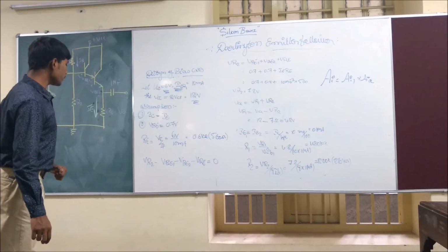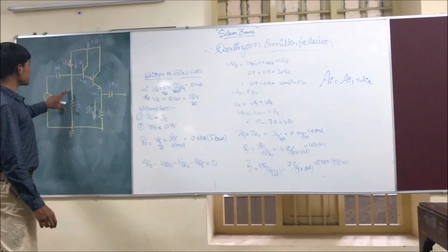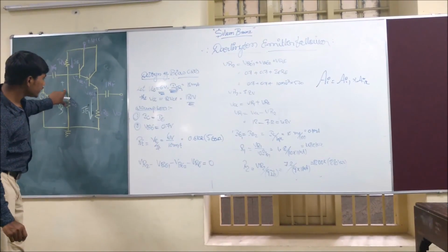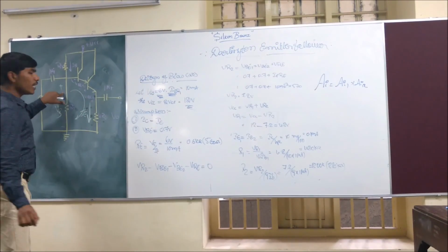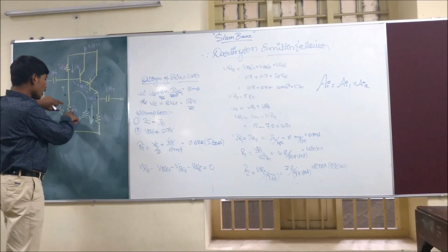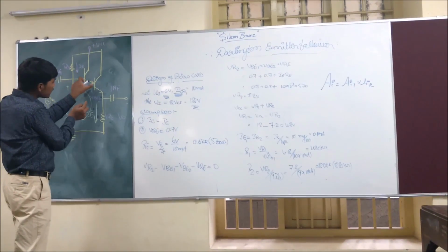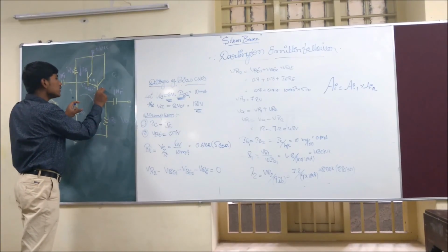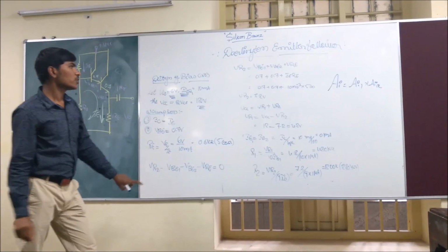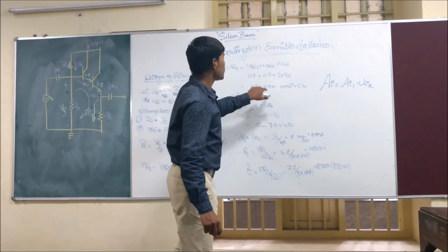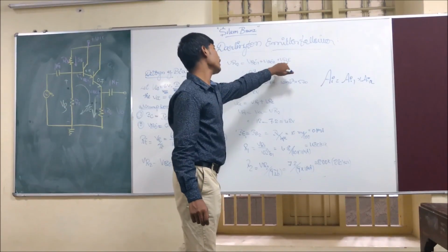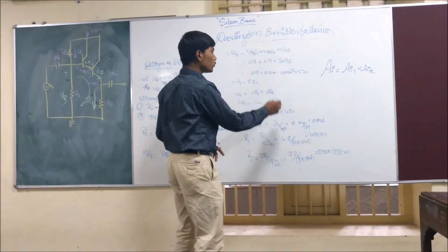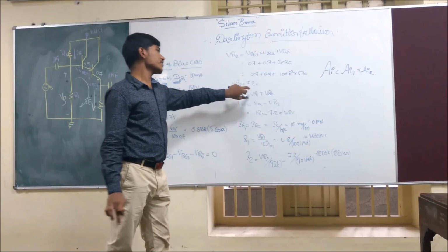The next step is the voltage across this, my biasing voltage. Let's call this VR2. This voltage equals the closed loop voltage, so let's apply it here: VR2 equals VBE1 plus VBE2 plus VRE. That's 0.7 and 0.7, plus the emitter resistor voltage, which is 6 volts. That gives a total voltage VR2 of 7.4 volts.